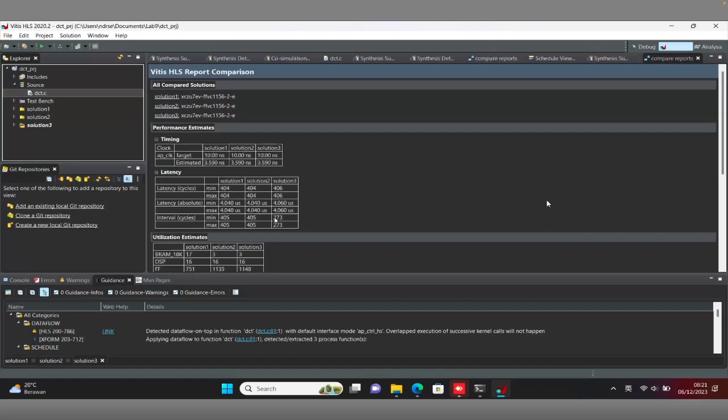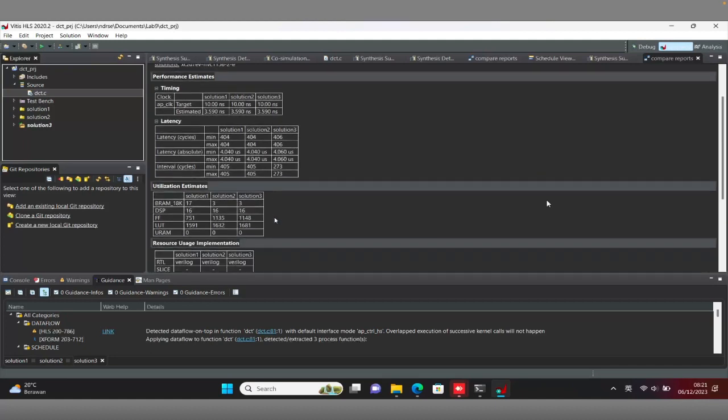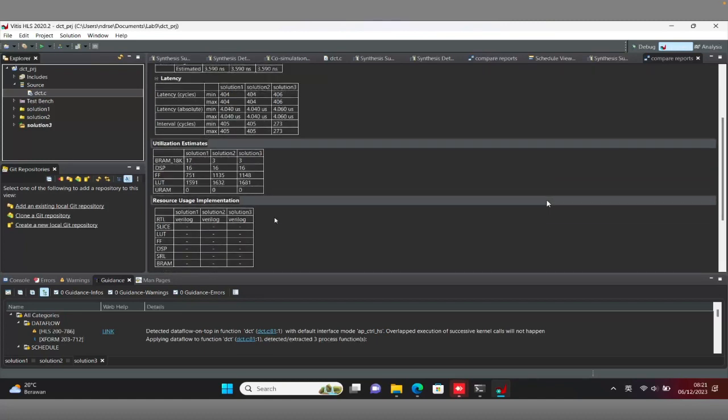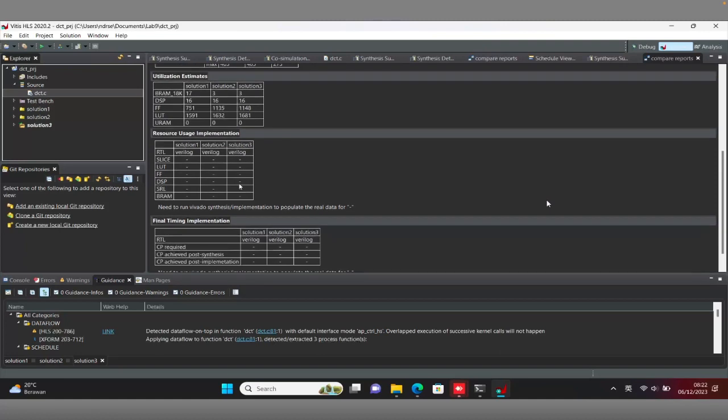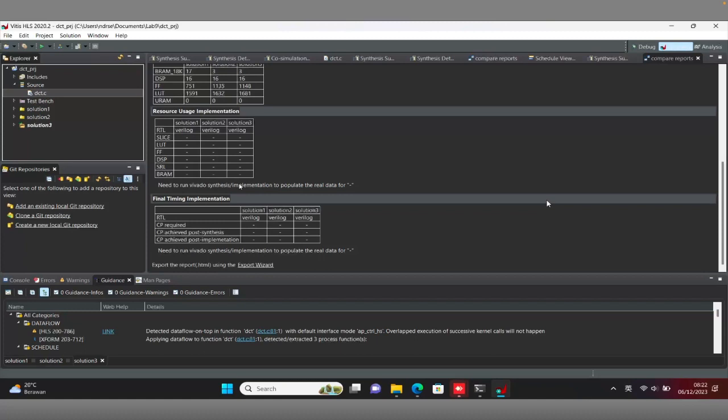273. This is our third solution. So the performance will be increased because the interval cycle is reduced compared to the previous solution after using the data flow. And we keep maintaining the memory usage, BRAM here, but just slightly increase the LUT. This is good for our design since only several LUTs are increased, which is still suitable and fits into our ZU7.